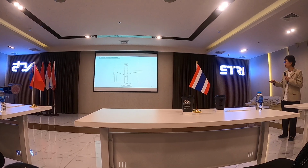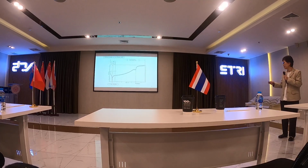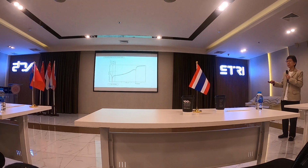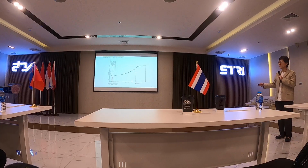And here this is the total plot. You can enlarge the potential range a little bit, like 100 millivolts around the corrosion potential. In this potential range, you can get a corrosion rate. And for the metal that has a passive film, you have to extend more until the pitting, the passive breakdown. We call it the breakdown potential.